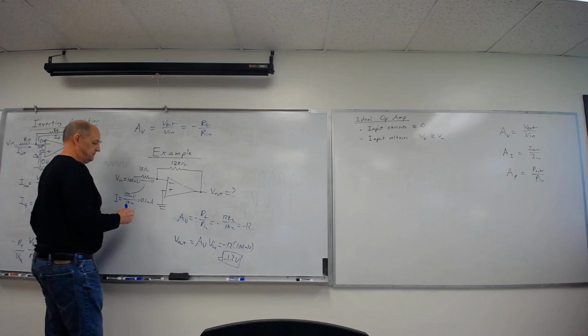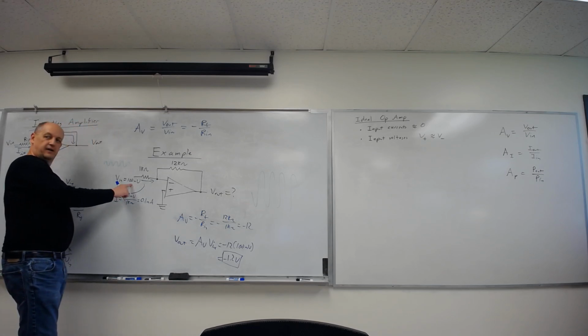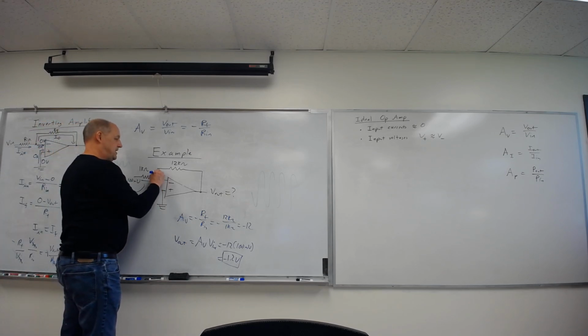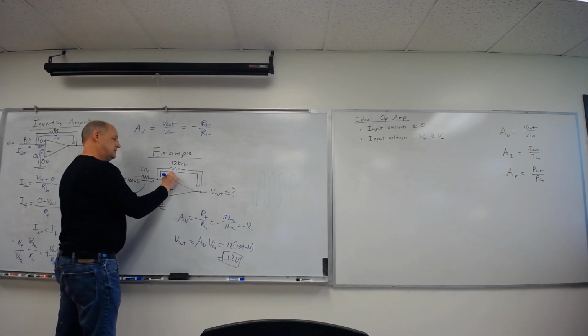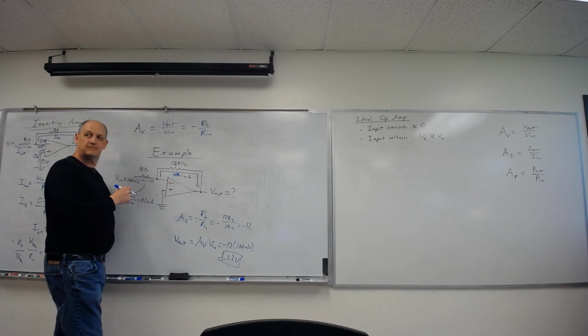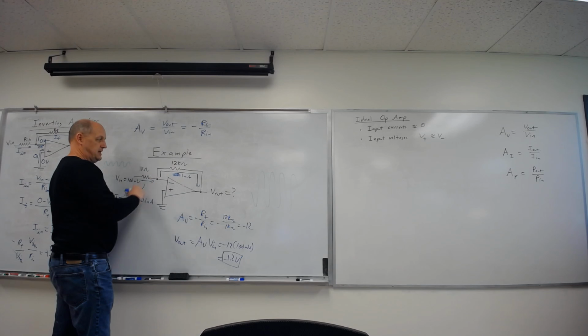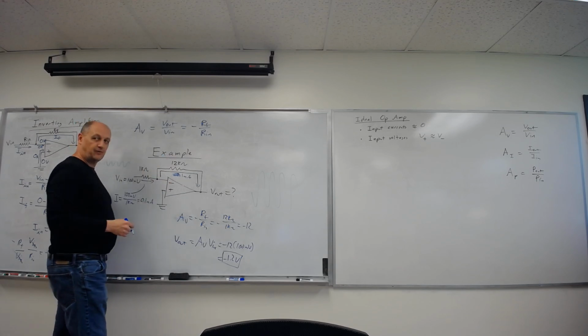So where'd you get the 100 millivolts, or did you just make that up? That was my input on my initial problem. Oh, right. That also means this current around here would be, oops, that's right, the input voltage, 0.1 milliamps. 0.1 times 12 is 1.2 volts.